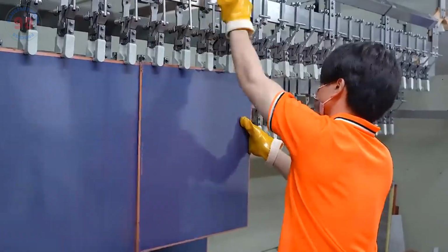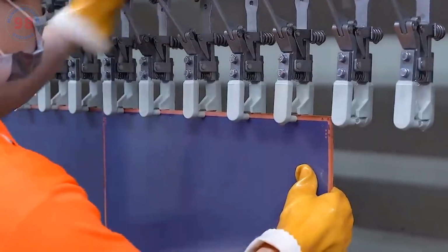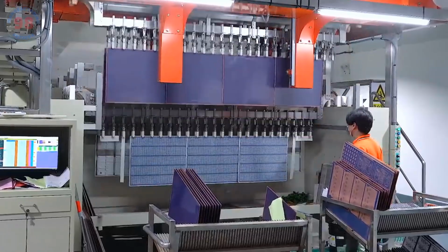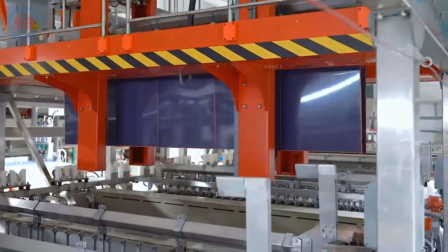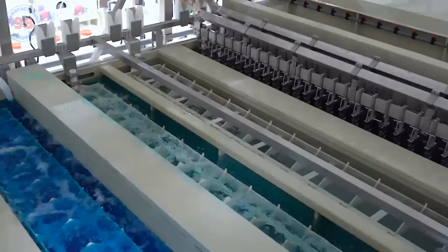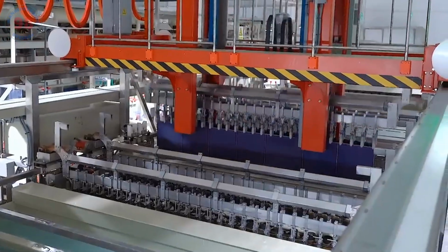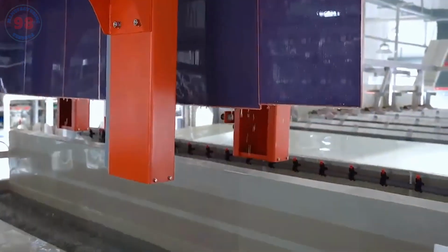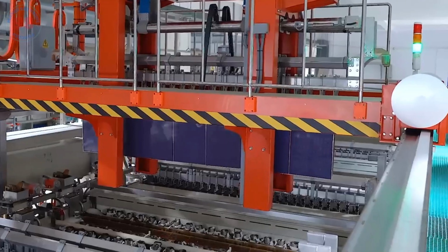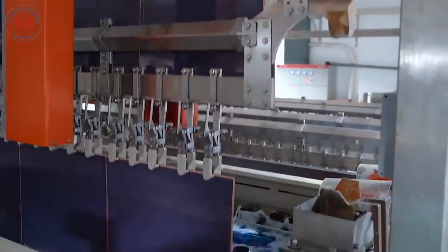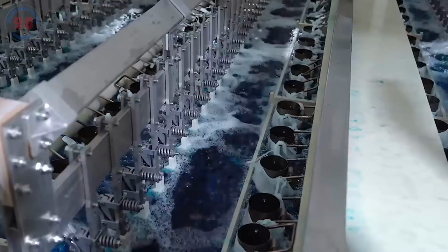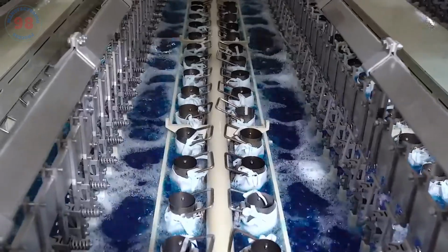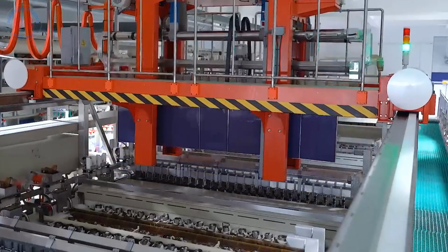Next, these copper-coated sheets are coated with a film. You see it in black, but actually it has all the circuit lines that have been pre-designed on the computer printed on it. The copper corrosion process also begins. The copper coating plate is in turn passed through a chemical solution. Thanks to the ink layer on the film, the circuit lines will be retained and the rest of the copper layer will be corroded to form electric circuits.